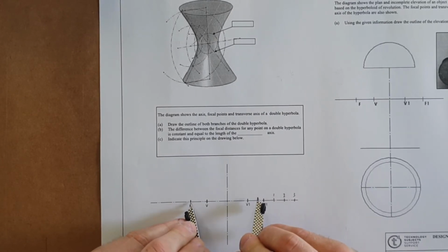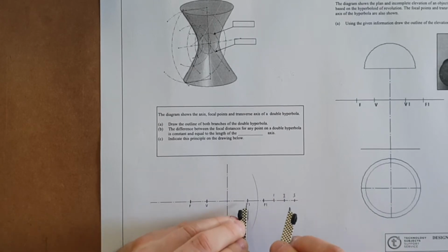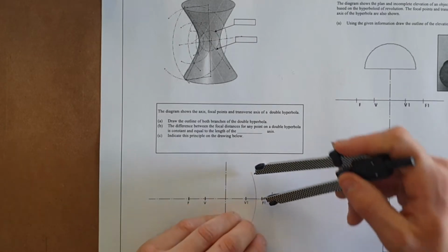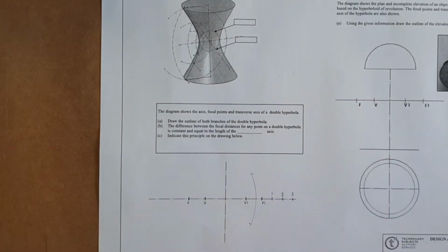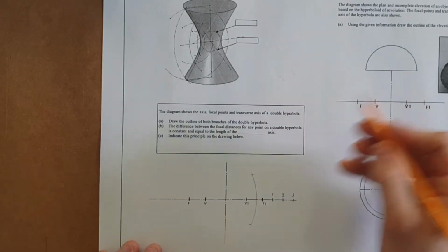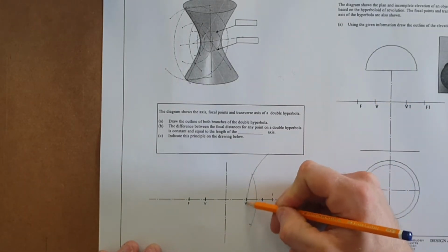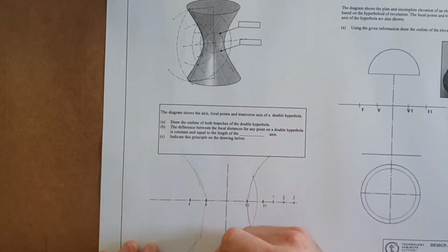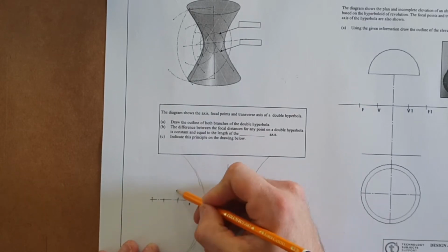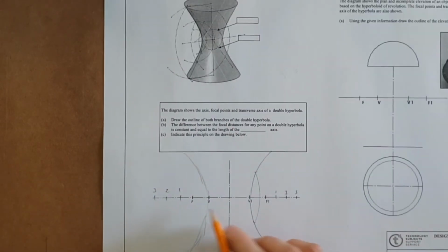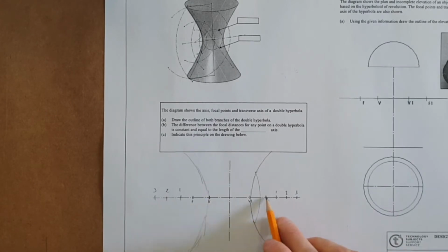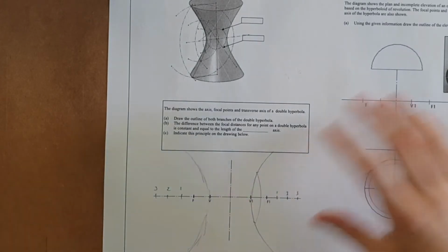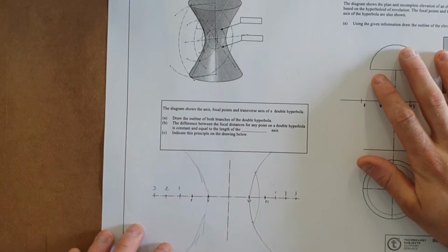And if you remember when you studied conic sections, it was always from the vertex to the point from the focus, and the same rule from the vertex to the point from the focus. And that was our method of constructing the points, which will eventually give you one hyperbola and the exact mirror image hyperbola over here. And obviously you'll plot out your points 1, 2 and 3 here on the left as well. So from the vertex to the point from the respective focus. You can now just practice the method used over here.